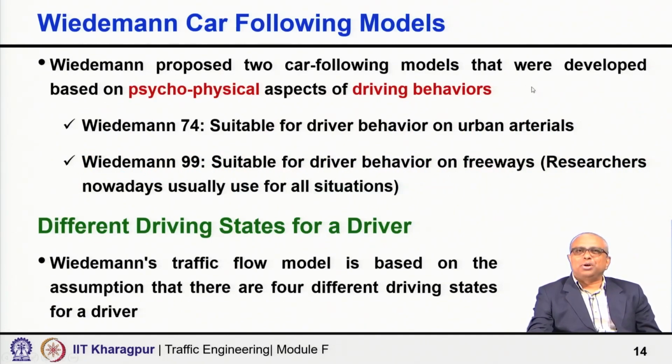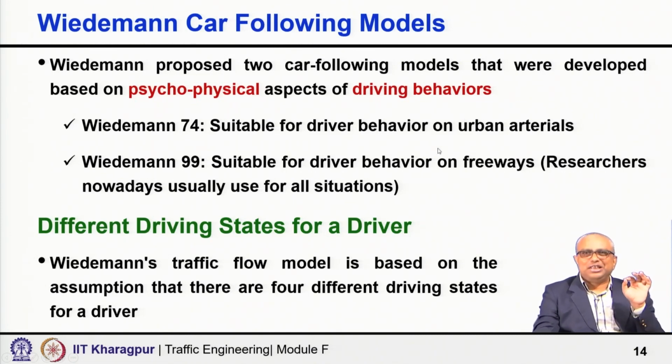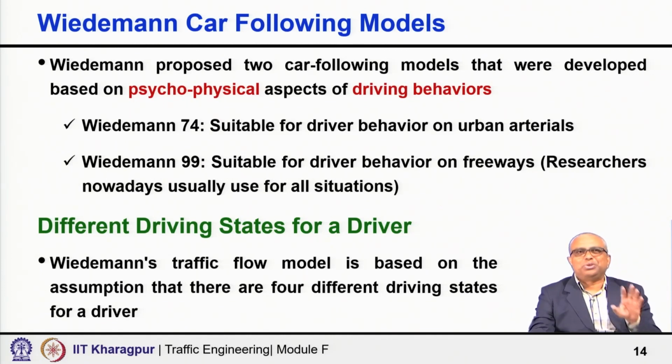Wiedemann proposed car following models that were developed based on psychophysical aspects of driver behavior, very interesting, and I really do not have much scope to go into details of this model, but these Wiedemann models are used extensively all over the world these days. Of course, the calibration and many other challenges are there. Local conditions have to be replicated properly, so it needs to be calibrated. The complexity is actually in the calibration process, which I will not discuss, because I just want to give you a quick overview of the Wiedemann model.